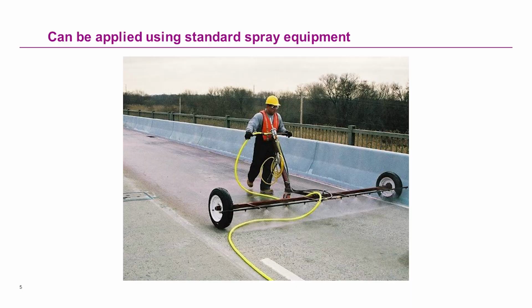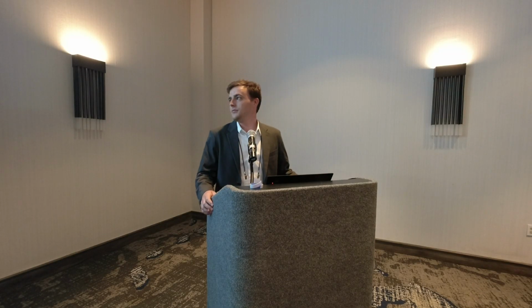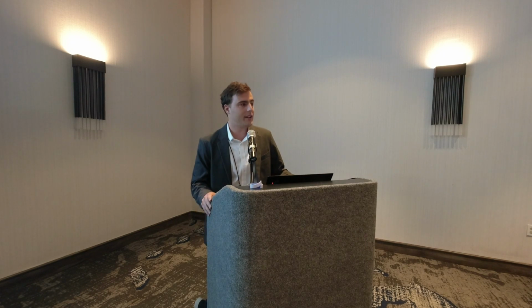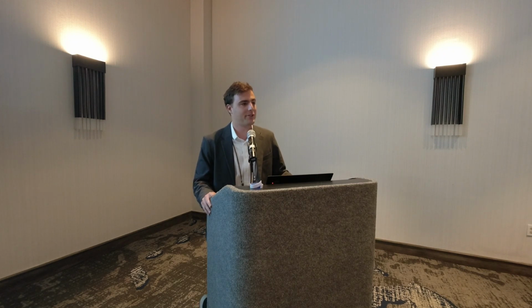This is our recommended DOT approach for applying the silane, a spray bar. I'm sure some of you have seen these before. They're pretty much just a rig with a garden hose and some spray nozzles on the end, attached to a pump and a compressor. Most of the manufacturers out there, including ourselves and our competitors, will loan these out to you. And you combine this with a 1 hour dry time, you really get the turnaround of bridge decks quite quickly, which I'm sure you guys are happy about when you don't get as many calls about bridge decks being closed.